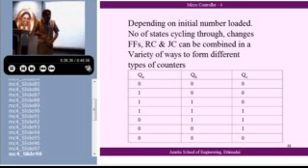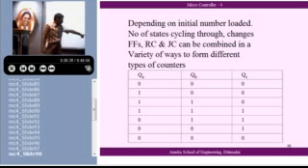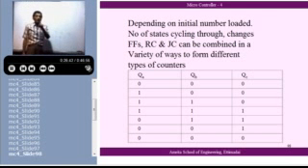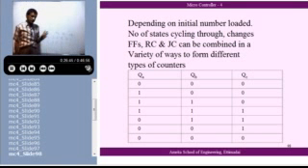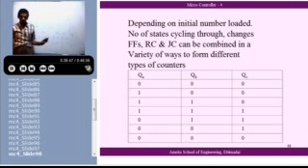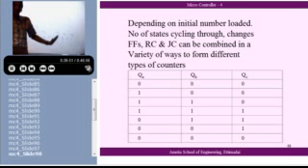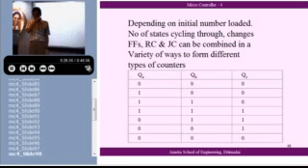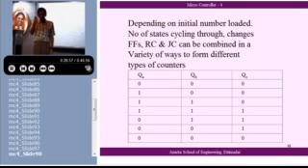But here, if I take this output directly, I know by looking at it which flip-flop count it is, 1 or 2, by just a direct look. I have got a counter with the decoder built in. With a binary counter, you have to take that 0101 combination, decode it and get the output as 0, 1, 2, 3. Here the decoder is not necessary.